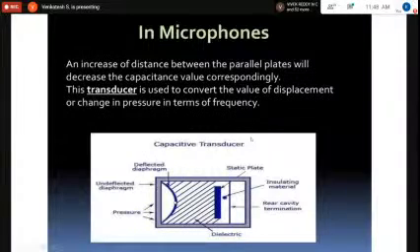So it vibrates. This microphone vibrates at audio frequency, and therefore the capacitance continuously changes because it is excited by an AC source. In this position, it is an undeflected diaphragm, and the pressure waves impinge here. This is a dielectric material between the two to get maximum capacitance proportional to the input sound signal, which is deflecting one of the plates with respect to this fixed plate, and the capacitance appropriately changes.